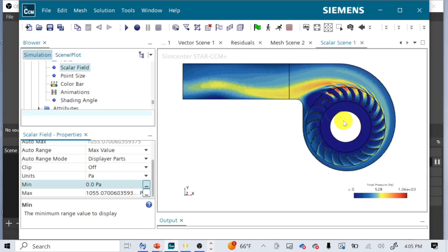So that delta P value, we're going to look at the difference in two things actually. We're going to look at the difference in static pressure. We're also going to look at the difference in total pressure. So change in total pressure and then also change in static pressure. Delta PT, delta PS. Technically, I don't need to write the S. If I just write delta P, I mean static pressure. But for the sake of comparisons, when we're talking about the fan curve and the delta P on the y-axis, you only still have to do 6 simulations, but you can measure both static and total pressure out of the same simulation and find the difference.